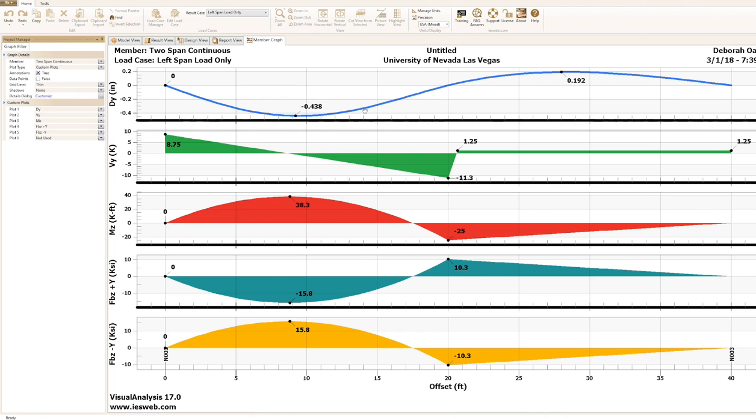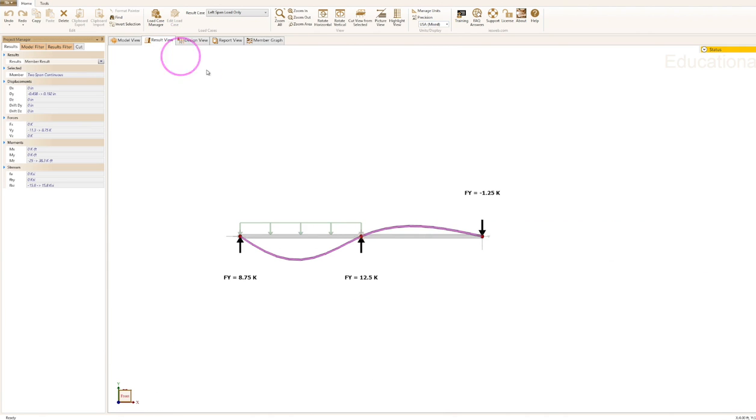And look at the form. Okay, so it is popping up. You might see that a little bit better in this view here. And we can turn on a picture view to show it as a solid member. So with this one span loaded, the result is to affect the span over here and lift it up. And actually it's got uplift on it right now.